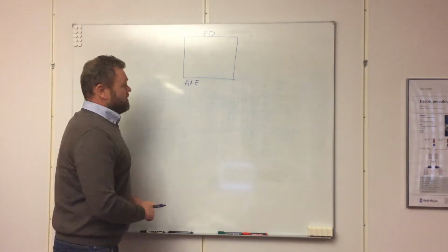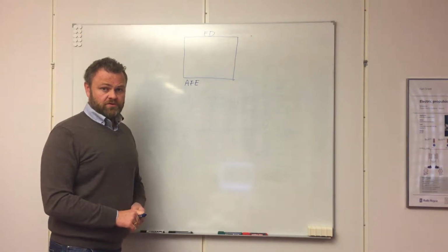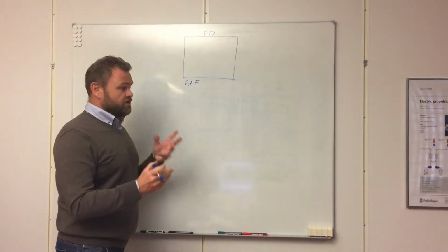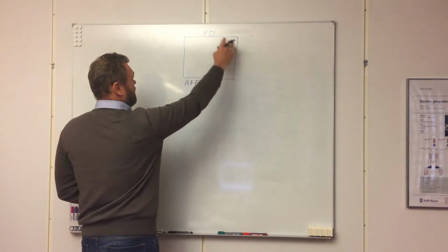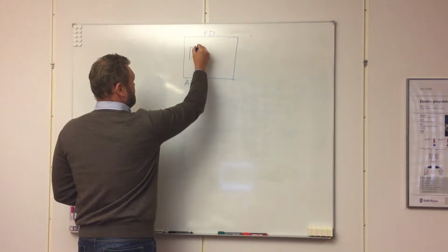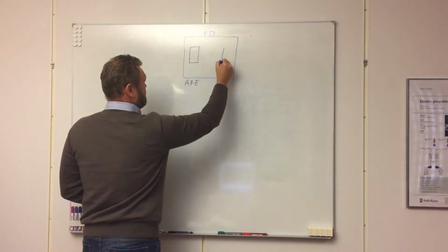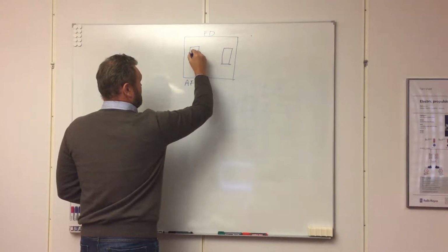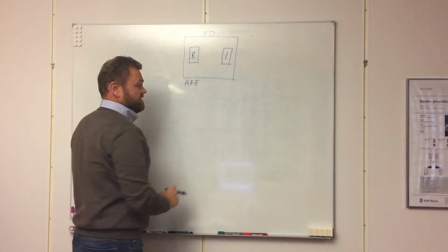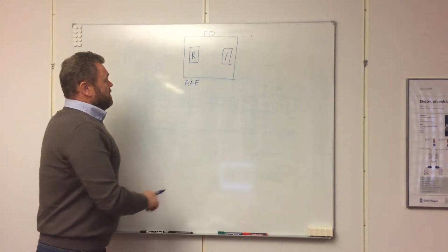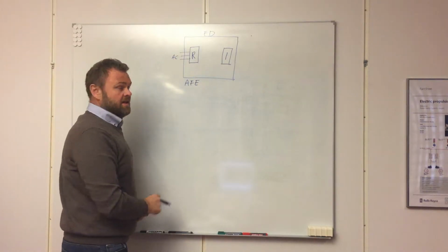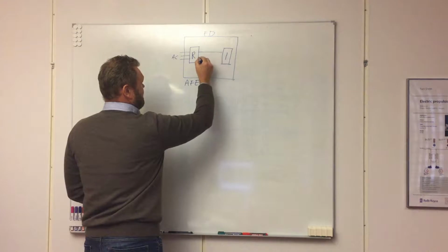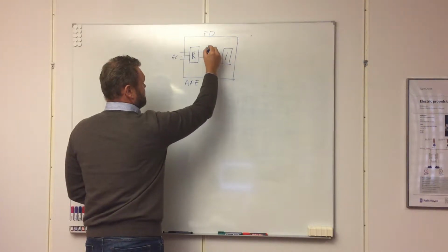Well, I hope you have seen the session where we talk about what is a frequency drive. Then you have some knowledge. Anyway, the frequency drive has two main components inside. It has a rectifier and it has an inverter. So the rectifier is rectifying the three-phase alternating current and making DC, plus and minus DC.